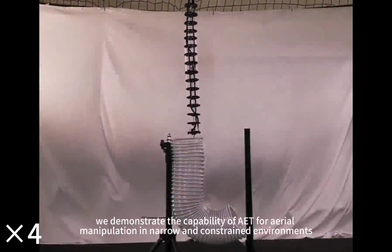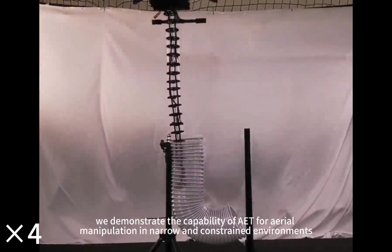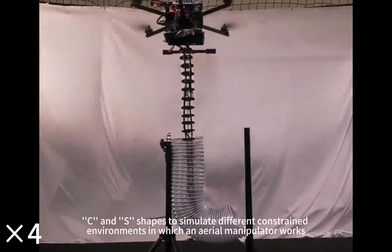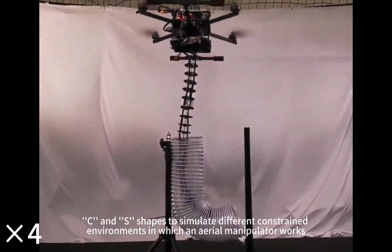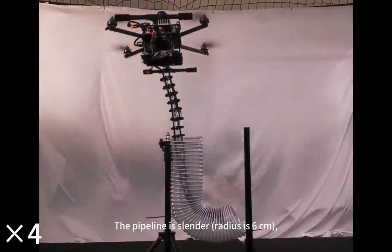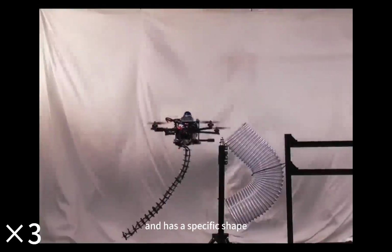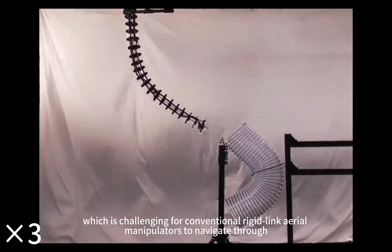Next, we demonstrate the capability of AET for aerial manipulation in narrow and constrained environments. We use a pipeline bent with L, C and S shapes to simulate different constrained environments in which an aerial manipulator works. The pipeline is slender, with a radius of 6 centimeters, semi-closed, and has a specific shape, which is challenging for conventional rigid link aerial manipulators to navigate through.